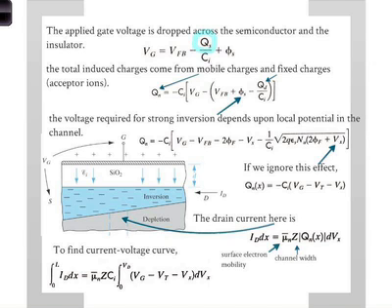Did you have something to say? I would assume that we have a very high negative charge on D, correct? Yes. So what does that mean? It means we're repelling the negative and making an area of holes. Correct. So this will become more depleted. This one is easy because it's just shorted, but here it's even easier because you're reverse biasing it even more. This is 0, remember? You reverse bias the PN junction, what happens? The depletion region becomes bigger.